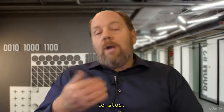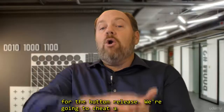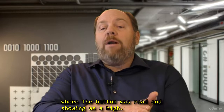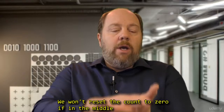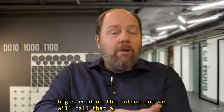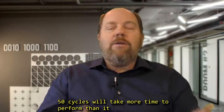So we're now going to modify our push button binary counter and throw in some loops and count how many cycles the button is pressed. And then do the same for the button release. Now we're going to cheat a little bit just to keep things simpler for this lesson. And we're simply going to count up 50 times where the button was read and showing as high. We won't reset the count to 0 in the middle of counting if we detect that the button was released from a bounce, for instance. We'll simply count up to 50 highs read on the button, and we will call that a single button press. This is simply assuming that 50 cycles will take more time to perform than it takes for the bouncing to stop.